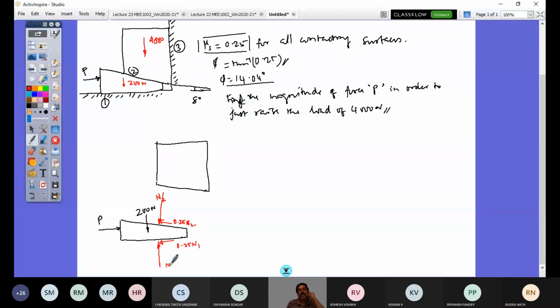Right. So again, there is an advantage of combining this. In wedge friction problems with a small angle, it is more convenient. If I combine these 4 forces, they can be made into 2 forces. That's always recommended, so we will combine that.